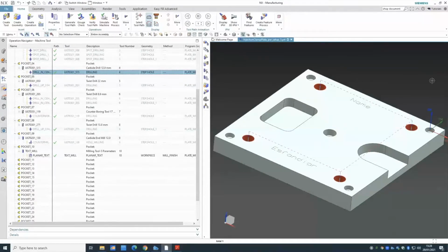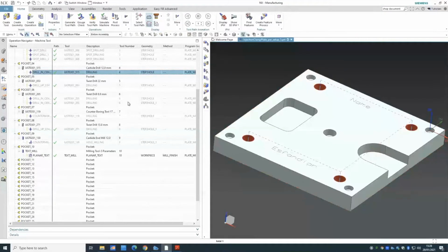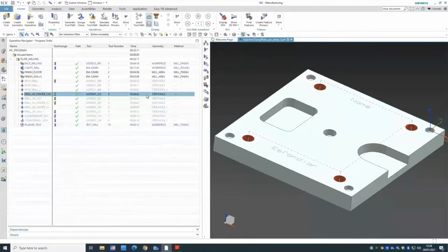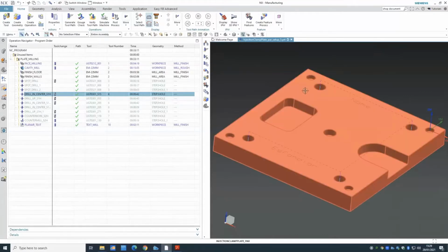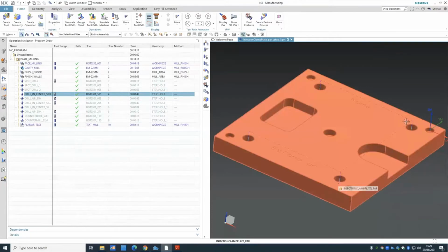You went from this hole to this hole, and from this hole to this hole, and you got a timing for it, right? You got the timing for that process: 42.37 seconds cutting, 5 seconds non-cutting. So I'm trying to optimize that 5 seconds non-cutting. I might ask why you didn't stop from here, go there, and then continue with the rest. Or why you didn't do it like going there, doing the zig and doing there.